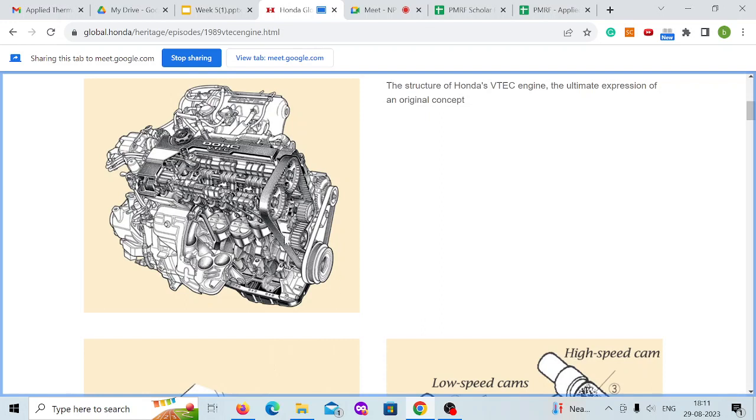And there's a motor connected, because for starting there is a starter motor. At the top, there are 2 gears driven by the crankshaft. These are the camshafts, which have cams. The cams are designed to time the valves: when to open and when to close, at what rotation and what angle the valve should open.